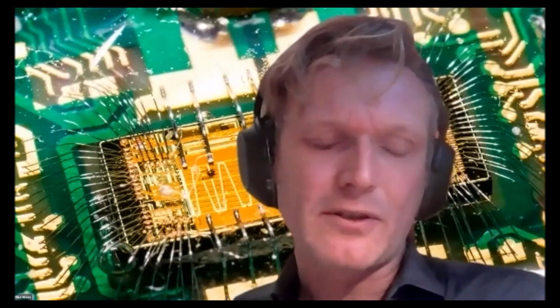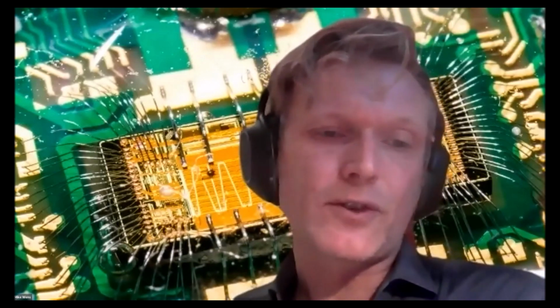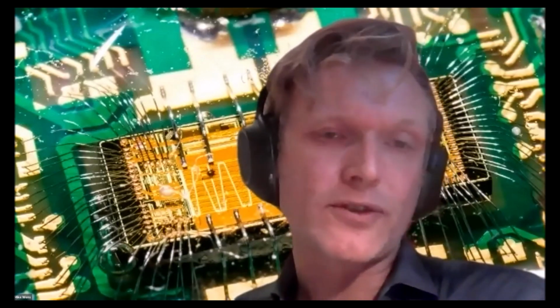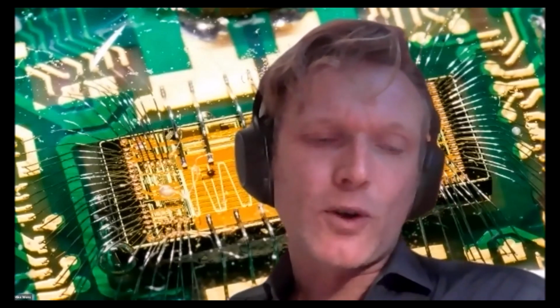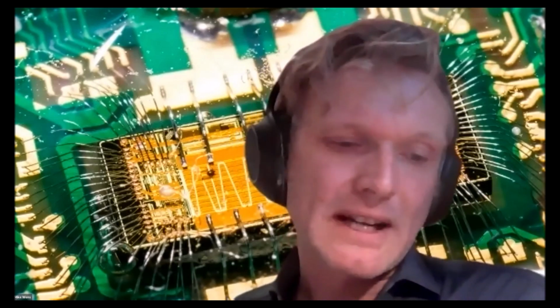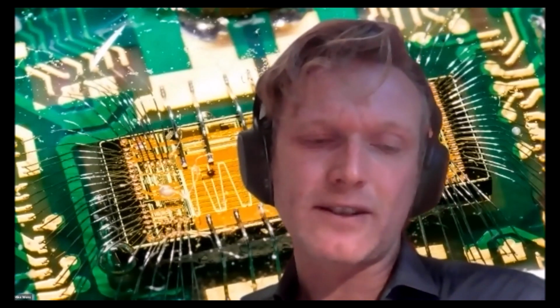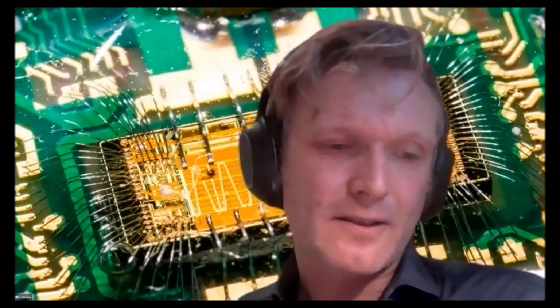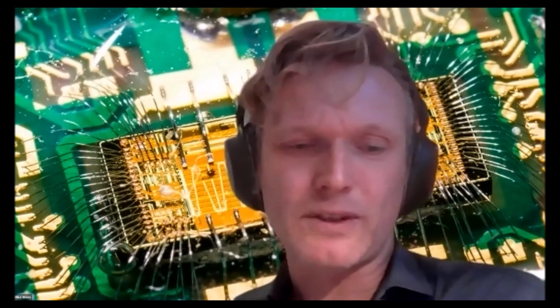And if you don't do anything about it, you will build up a too high voltage compared to what you have intended, and eventually you will stress the gates of your GaN device, and you might break it or cause a reliability issue. There are many ways to deal with this. Of course, you need to minimize inductances. That's clear, but I think that's opening a door that's already open.